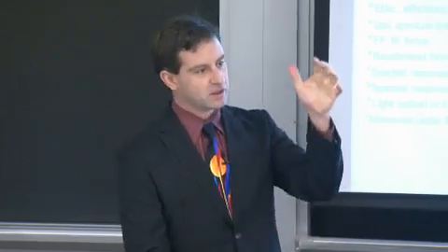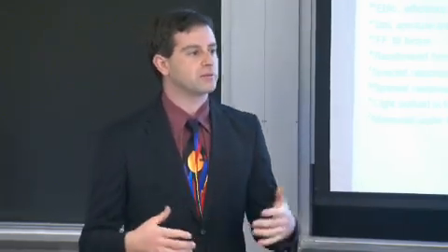In other words, in that large specimen, there was one point that was extremely weak, another point that was sort of weak, and another point that was mildly weak. Right? And as you increase the size of your specimen, the likelihood of having one of these failure points increases. And that's an analogy, let's say, to a large area module as well, that we could have pinholes or other manufacturing defects inside of a large area module that could reduce the performance locally, and because everything is interconnected, it tends to drop the performance overall.